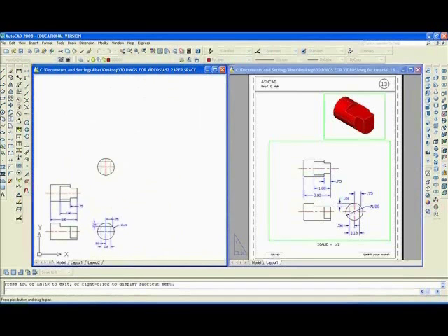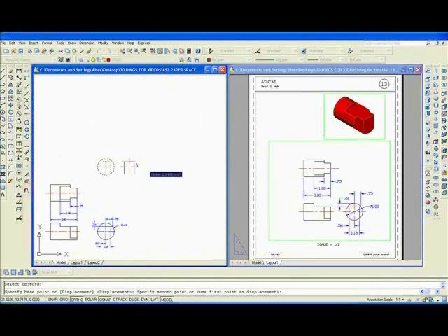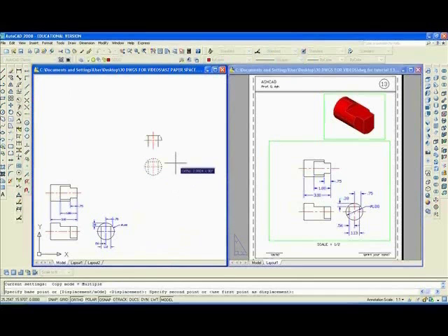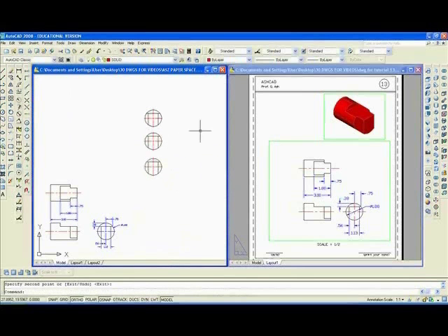And I'm going to move M into the solid thing, put it over here, say like that. Also, I think I'm going to have to copy it. So I'm going to type CO enter or copy. I'll copy it 3 times. I'm not quite sure why yet. Let's zoom in on a couple of them.